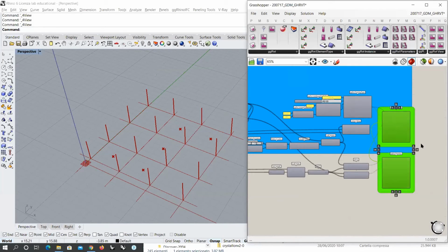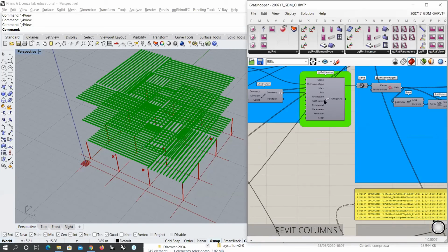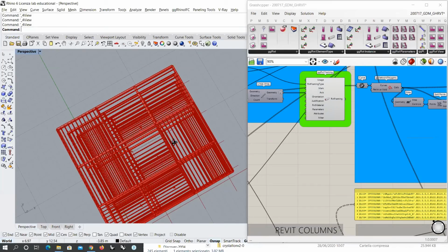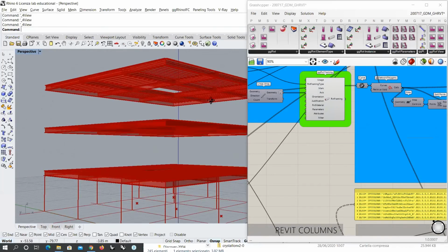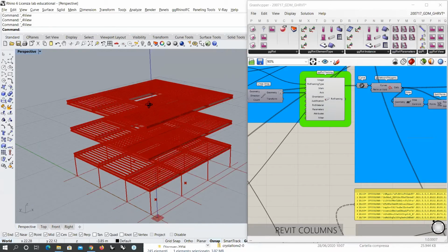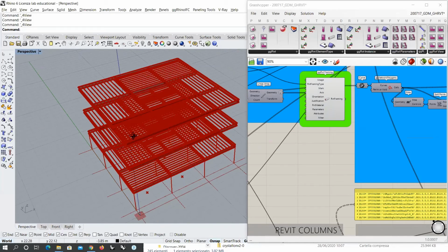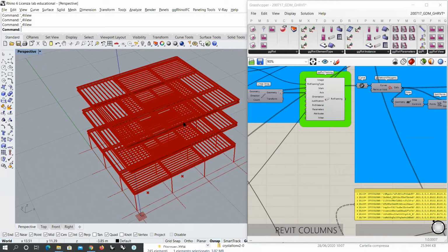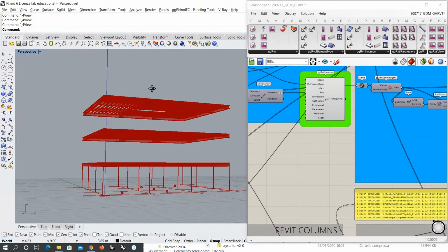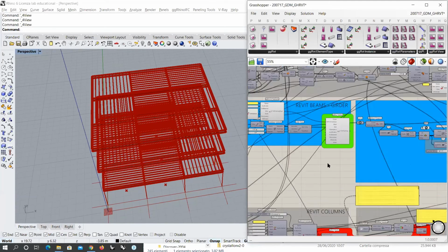And so we have a complex set of structural elements here because we have two orders of beams, taking into account also the shaft for the stairs, which is leaving these areas empty. So, for example, in this particular scenario that I'm considering, it's important to consider where you are drawing or placing the stairs, because this is affecting also the secondary beams, of course. So let's jump to the stairs.